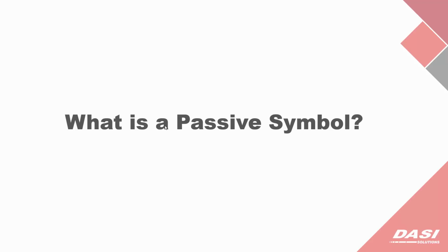Now that's in the bill of materials, that you've got a manufacturer for that you want to have purchased? Well, obviously that's not the case. So there is this thing called a passive symbol. Passive symbols are symbols that do not require any circuitry. Consider maybe it's a note that you might put on your prints on a regular basis, or a figure that you wanted to put, maybe it's the DIP switch settings that you want to put on a specific PLC. Those types of things are passive symbols that you could still put into a library, but they're not going to